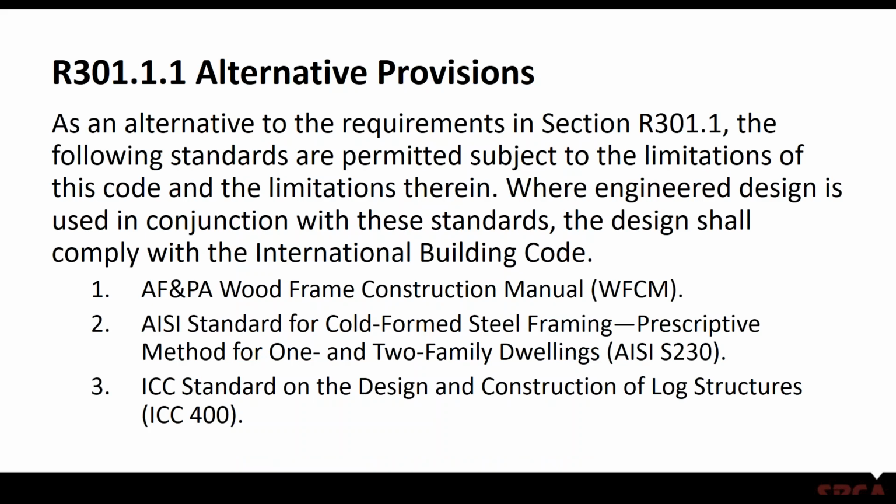There are alternate provisions that are allowed in R802.1.1. The following standards are permitted, subject to the limitations of the IRC and the limitations in the standards. And then again, as we mentioned earlier, when you get into these situations, certainly engineered design can be done, and that needs to be done in compliance with the International Building Code.